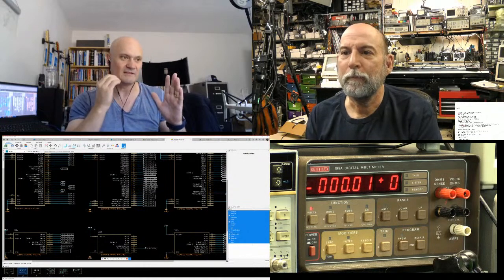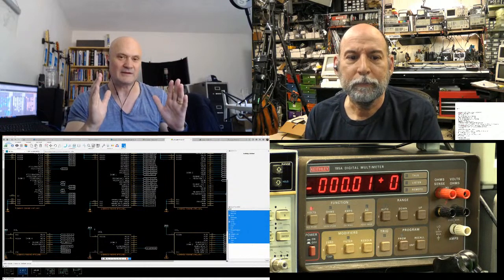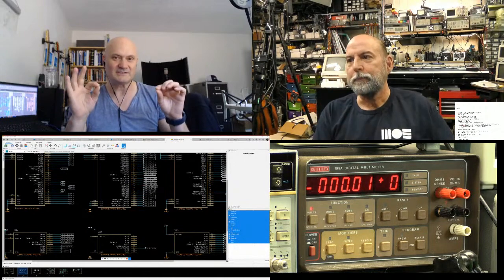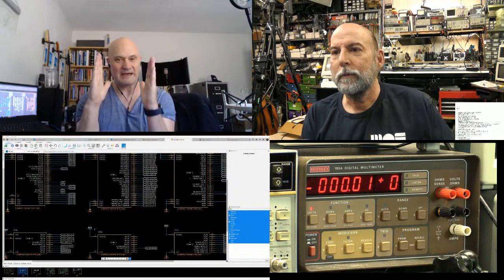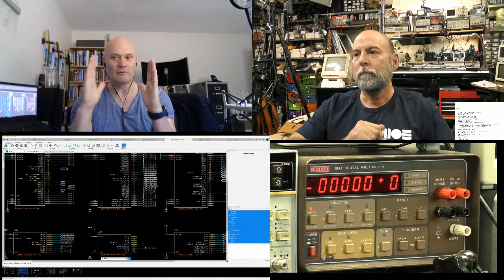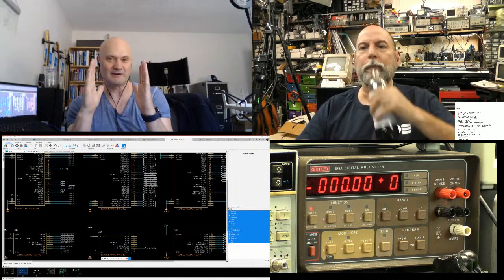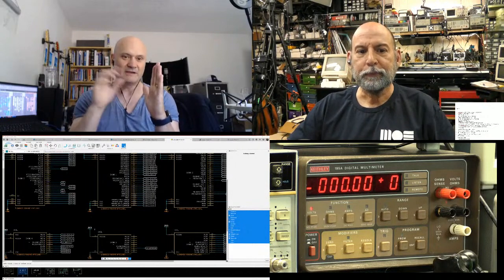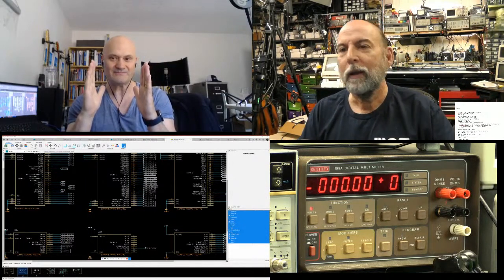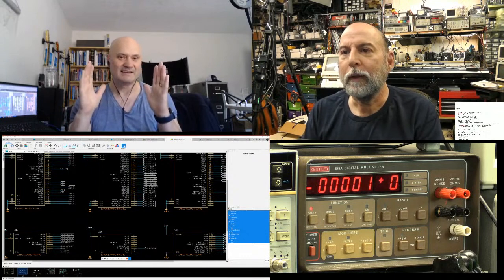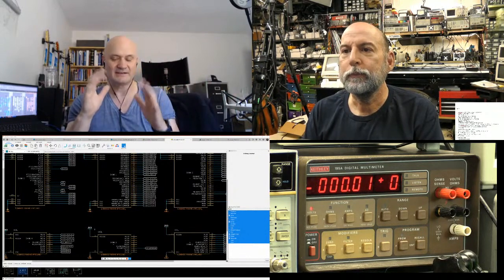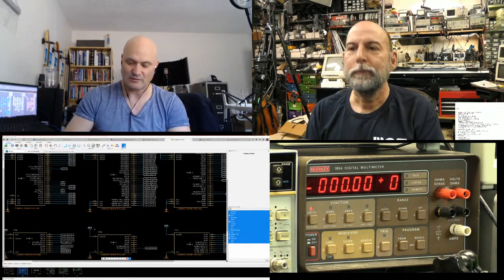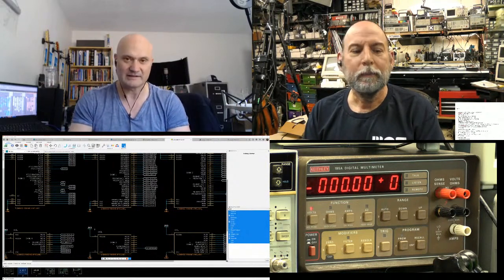So the key IP in the Digitech Whammy pedal was that it had zero crossing detection on every waveform, and they would vary the window or wavelet sample size to match up with a whole wave of the instrument's signal, and then splice that and blend it in so that you didn't have any glitching, or less glitching. It was still glitchy, but yeah.